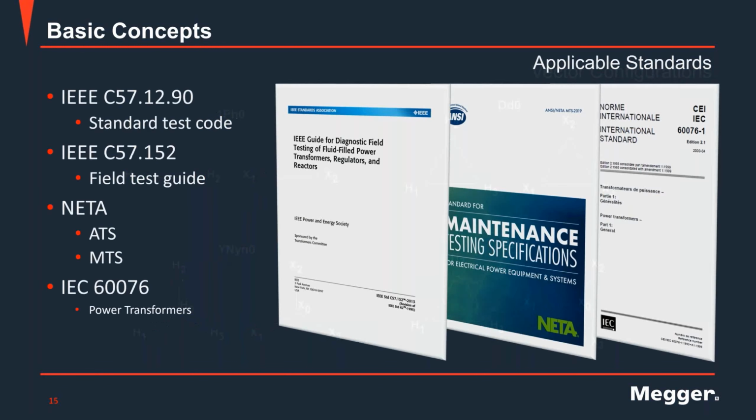I also mentioned that we need to compare these values to our nameplate and then determine if my measurements are within the limits. What are those limits? The IEEE dictates plus minus 0.5% of error when compared to my calculated value from the nameplate, my transformer nameplate ratio. And I'm showing you as a reference.